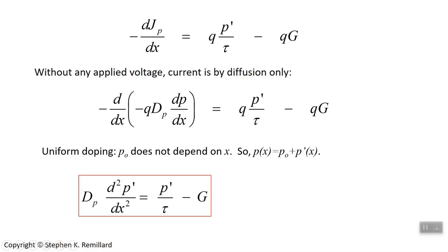I factored out the big D and the q. You can call that the continuity equation. That's what we're going to use, and there's an equivalent one just for electrons. Replace the p's with n's. That's our continuity equation. It ensures physical nonsense doesn't get realized, because what goes in will be what comes out. And so we're going to use that quite a bit now in the rest of this chapter. So stop at that.